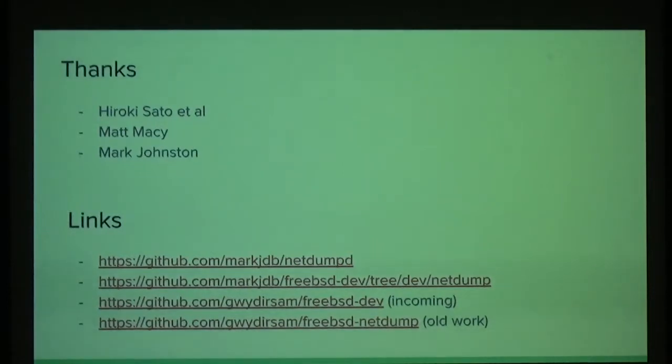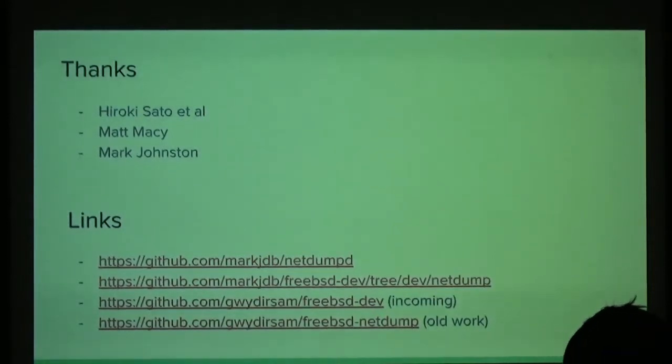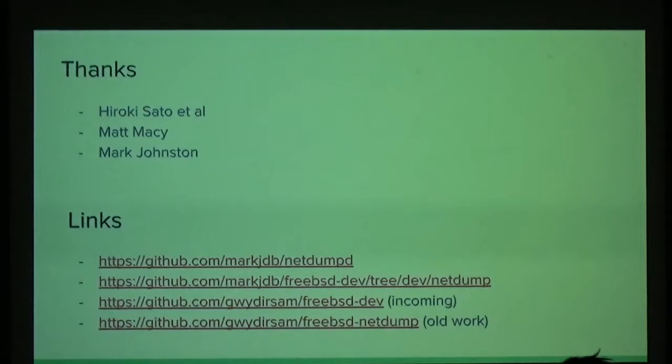Another question is, what about the watchdog? Because when you are creating a crash dump, you can say that after this function, bump the watchdog itself. But if everything is dumped, we create the crash dump and we are sending it over the network, and especially with those transmission issues, the watchdog will just kill your machine, right?